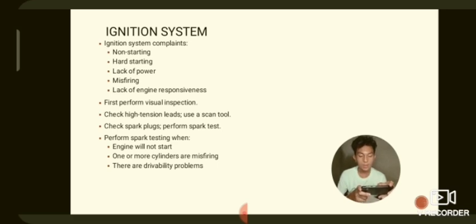These are the possible problems of our ignition system. The ignition system ignites the air and fuel mixture in our combustion engine, so the problems are non-starting, hard starting, lack of power, misfiring, lack of engine responsiveness. This is what we check in our testing. So, next.